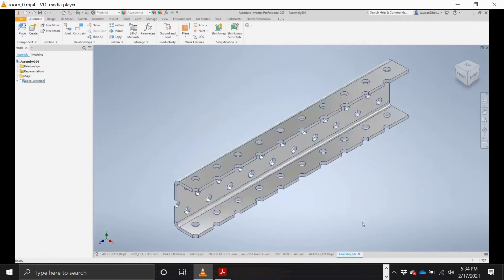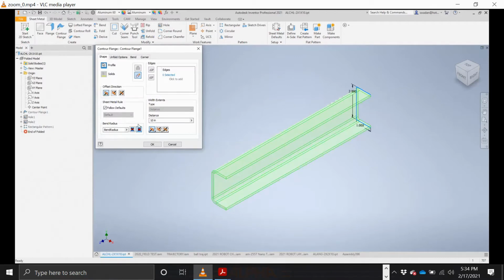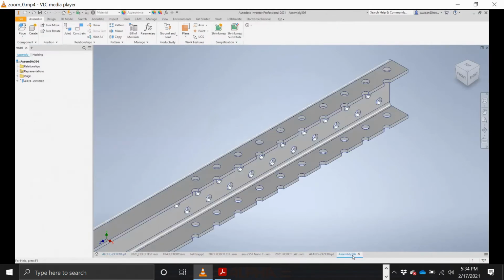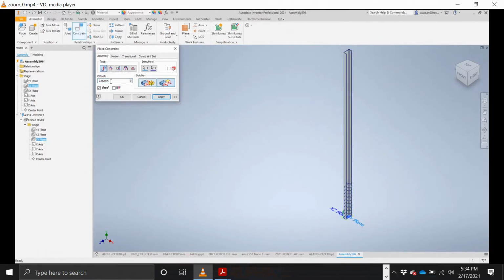And I'm going to have to mate that to everything. But first I'm going to change this length to, let's say, about 50 inches. And so now I've got a 50-inch long piece, and I can save that off onto a different component. I can make multiple copies of that of different lengths. But right now I'm just going to take that one piece that I have and mate it to my origin at that 5-inch offset.